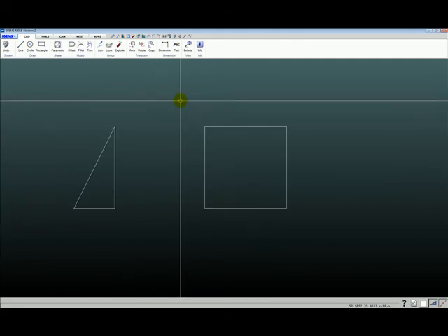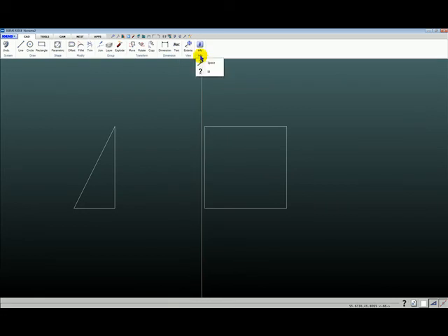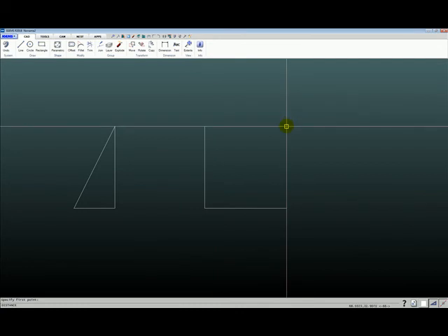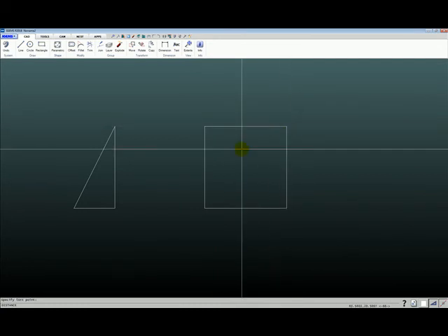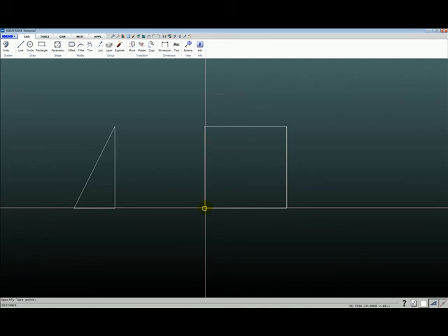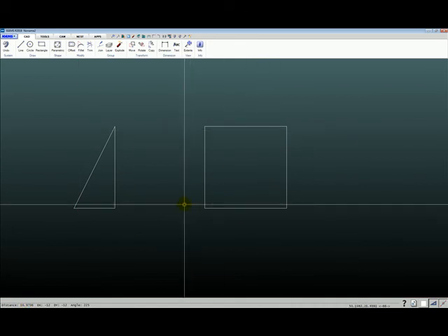Another command that I find quite useful is the measure tool, which is found under the info submenu. So you can click on the info button there and then go down to space, or you can press Control D on your keyboard. If I wanted to measure this square here, click on this corner, click on this corner. Since my snaps are on, it picks those corners. And then down here at the bottom, we see that it's 12 inches in X, 12 inches in Y, and then the 16.97 would be the diagonal across there.